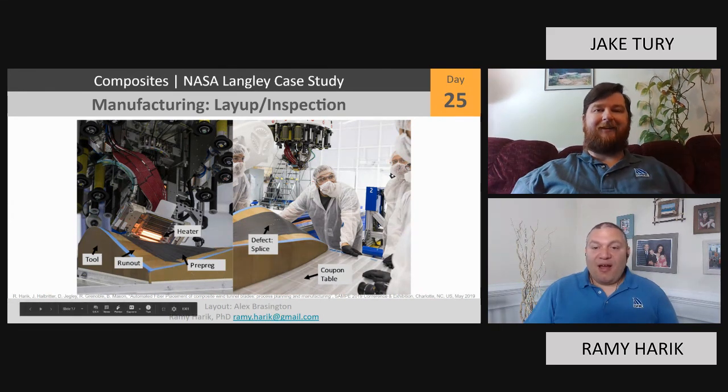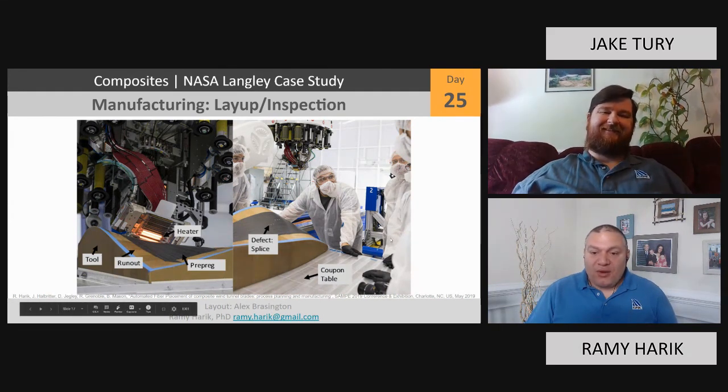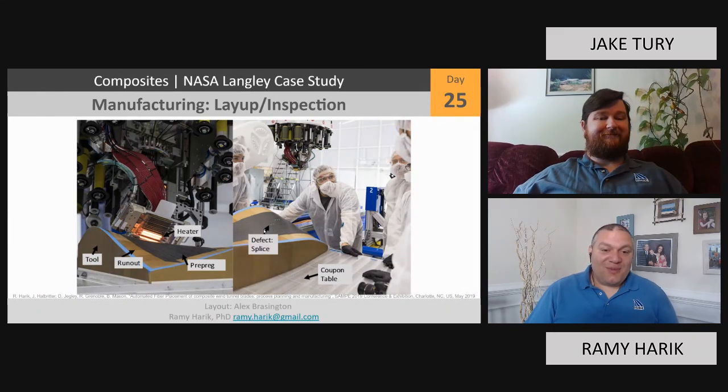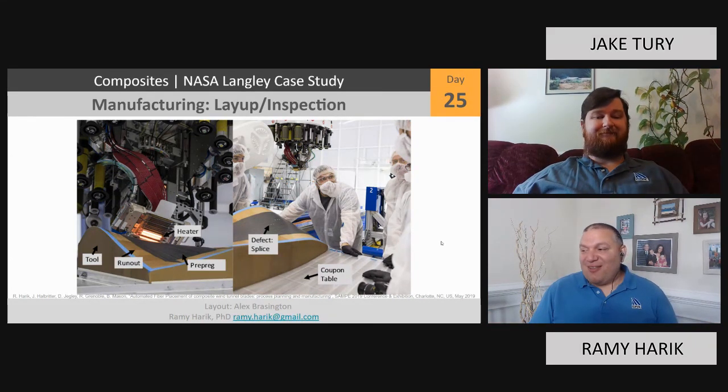And after that, we go around and take a look after each layup. We make sure that the splices are fine, or if there is an AFP defect, sometimes we accept it, sometimes we don't, and we have to replace it and do the arts and crafts. Do you agree with this name, arts and crafts?